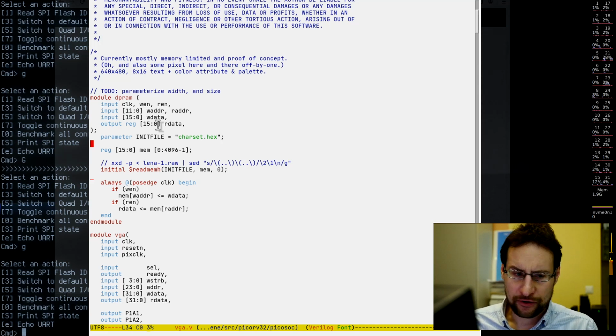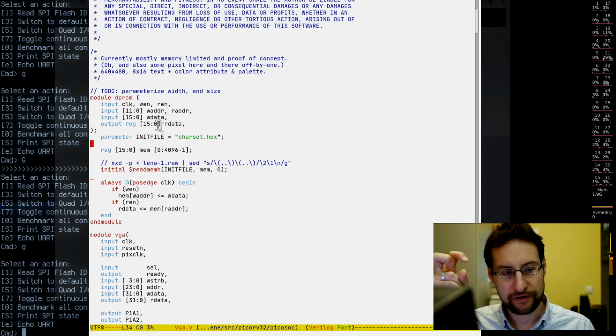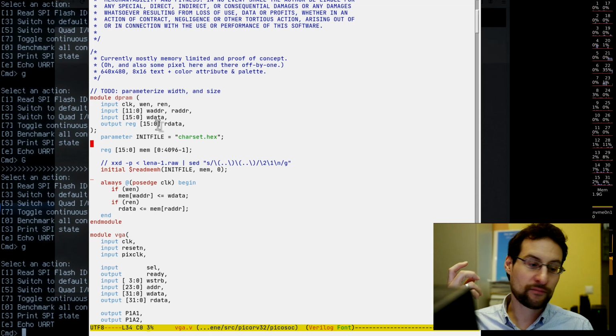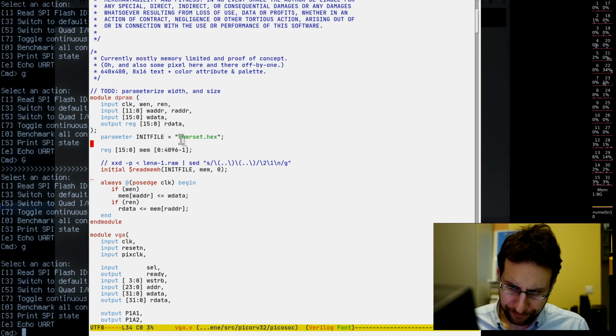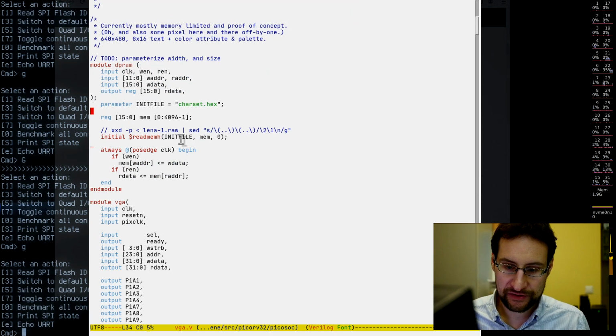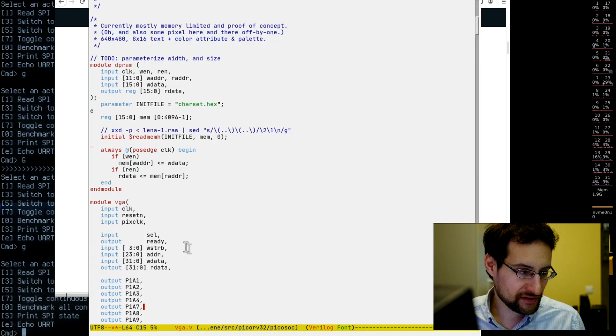Yeah, I actually employed quite some tricks to get that far. And so we have amazing sound, well, 3 voices and random noise, kind of amazing noise. And this video core, and right now I have only 10 or so logic cells left. Most likely I have to strip down some features or optimize this a little bit to have keyboard and mouse, the last missing point. That will be a little bit challenging, but maybe more on this later. I hope I don't need to strip so much out. Certainly I don't want to strip something out, but yeah, 5,280 logic cells.